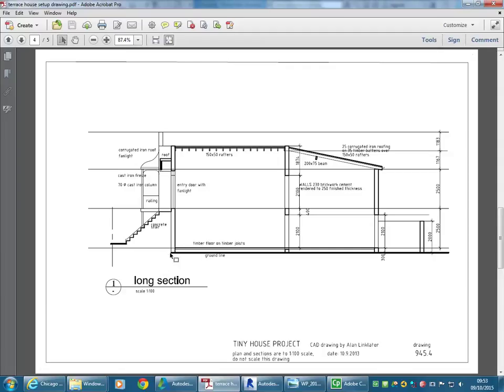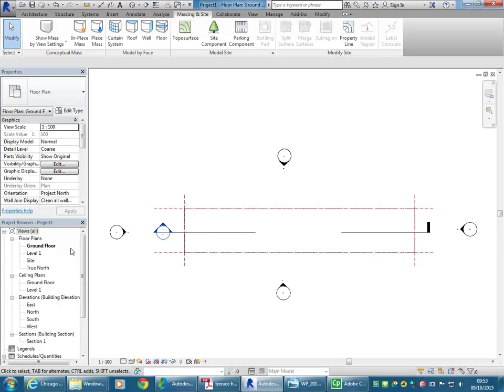And so the way you should be thinking when you create levels in Revit is to start with the lowest level that you think you'll need in the project overall. And what I found with Revit is that this ground floor level that you are given in the Australian architectural template is good to have as the lowest level.